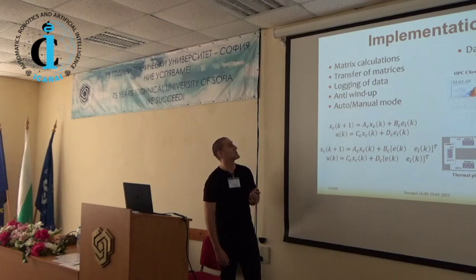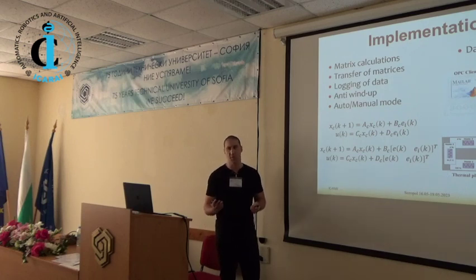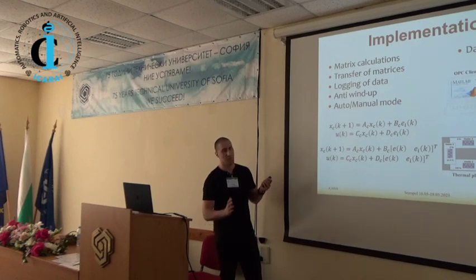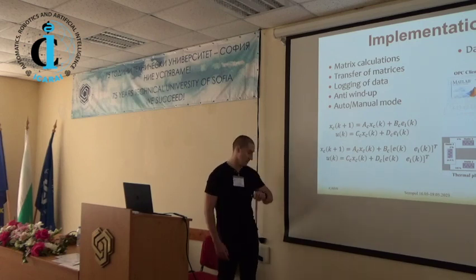Some problems: there are no ready available functions for matrix calculations. So we needed to write some simple functions just for matrix addition and matrix multiplication. There is, of course, some anti-windup mechanism by back calculation, possibility of overflowing data, etc.